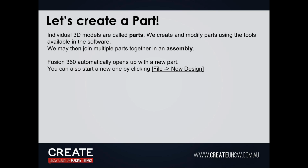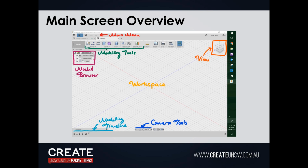Now, I'll just go back to this slide. So we've already gone to the part where we've opened File and New Design. If I'm going too fast at any point, just stop me and we'll continue on from there. So I've gone over most of this. There's a timeline here on the bottom. So if you ever make a mistake and you realize that you wanted to edit a dimension that you've already changed 5 or 6 steps before, you can go back into here and you can change that dimension.